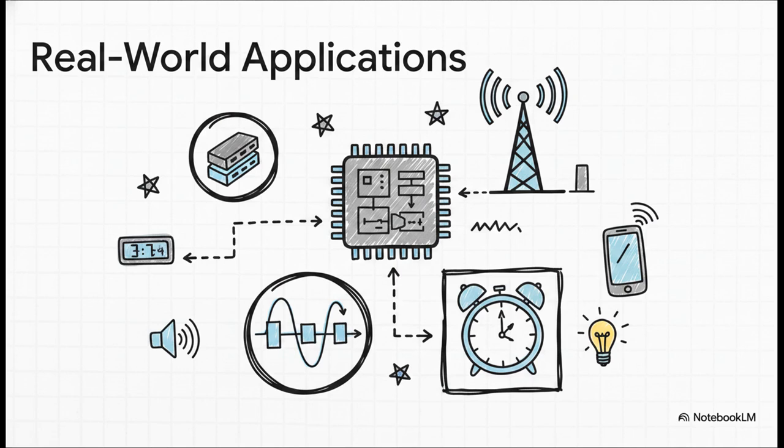Registers are the beating heart of CPU and memory systems, juggling status flags and math operations. Shift registers are what makes serial data transfer between remote systems possible. And counters? They are doing the heavy lifting in almost every device you own. They handle frequency division and telecommunications. And honestly, if you glance at a digital clock, you are literally looking at decade counters ticking away the seconds and mod 6 counters wrapping up to 60 for the minutes.